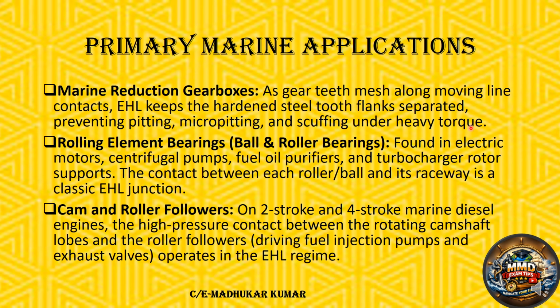Rolling element, ball and roller bearings. This is found everywhere: ball and roller bearings in motors, centrifugal pumps, fuel oil purifiers, turbocharger rotors and so on. Wherever you find roller bearings and ball bearings, at the contact points, either the roller contact point or the ball contact point, they have elastohydrodynamic lubrication. Cam and roller followers in 2-stroke and 4-stroke marine diesel engines: high pressure contact between the rotating camshaft lobes and the roller followers, driving the fuel injection pump and the exhaust valve.